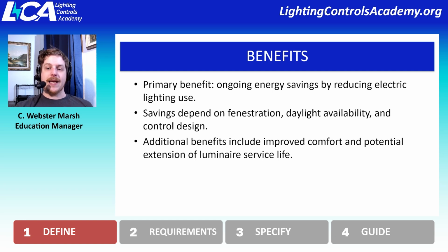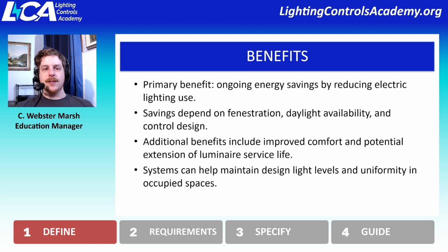Depending on how intensely you use them will determine how quickly the LED loses its capability of emitting light. So if you keep everything at a lower level, at a dim state, the lifespan of that fixture will last a lot longer than if it was always at full output.